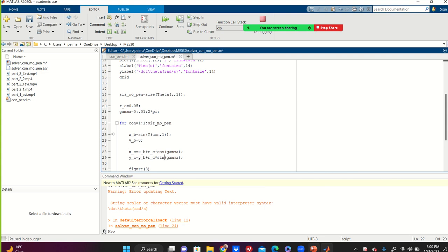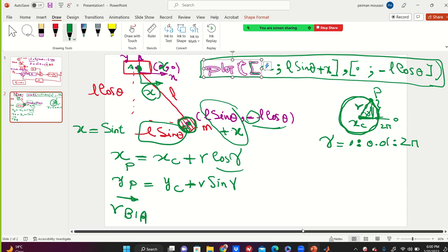Exactly what I did. You see, I started from a complex problem. This is the whole picture, guys. You as a control engineer, you're gonna do that. You start from a complex problem using the basic dynamics course that you passed here, using Newton's second law and the moment equation for the mechanical systems. I'm gonna cover all the systems. You're gonna derive the differential equation. If it's nonlinear, you're gonna linearize it at an equilibrium point.